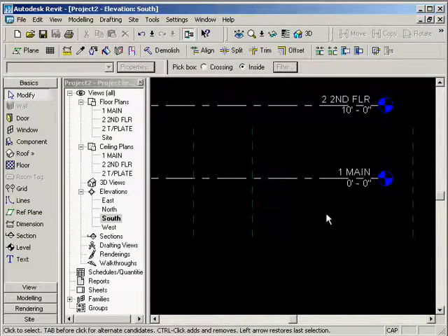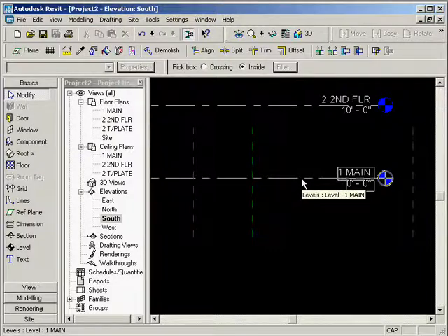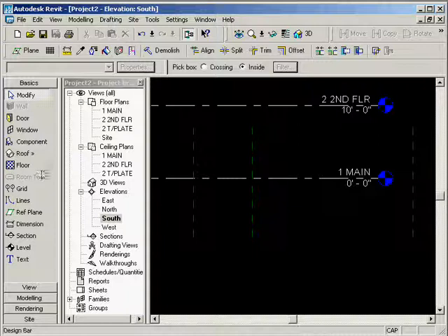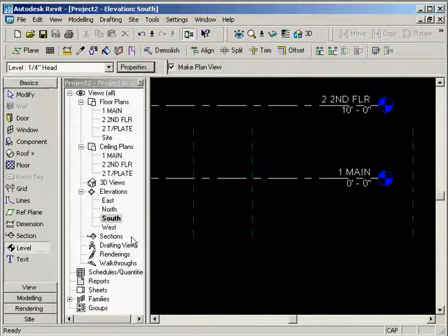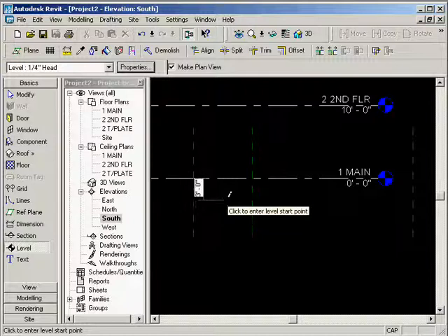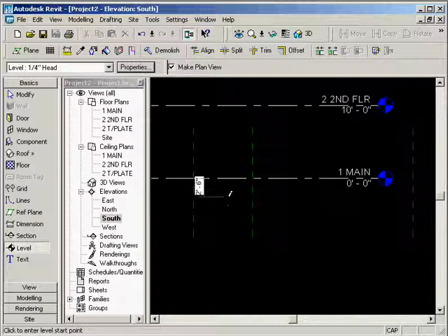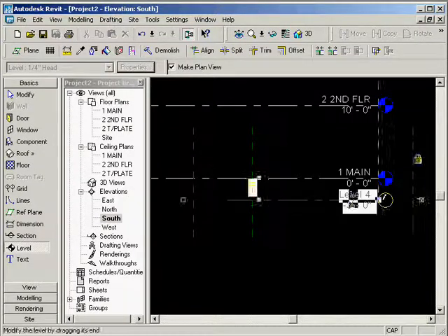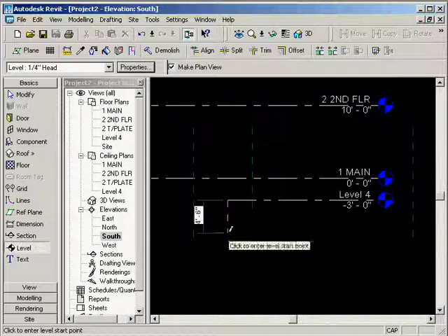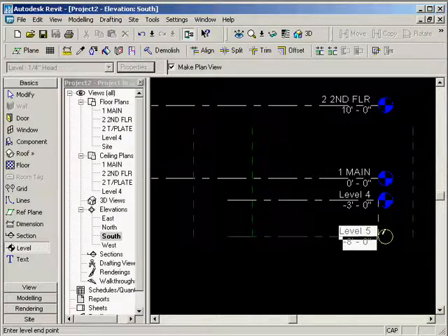So now below the main floor, we're going to have some negative levels with an elevation of a negative number. So I'm going to go back into here. I'm going to add my next one in, and I know this one is going to be the top of my slab in my garage. So I'm going to just click on here and bring this over. I'm going to create another one as well down in here. I'm going to create 3 more.